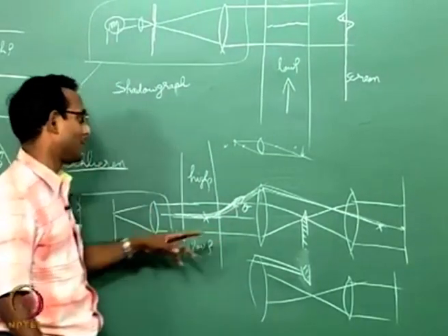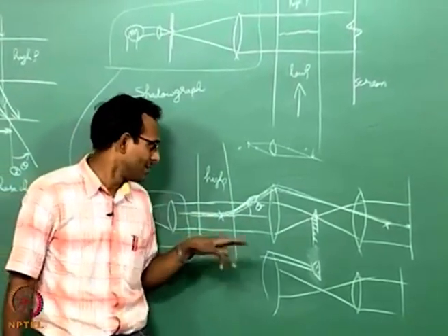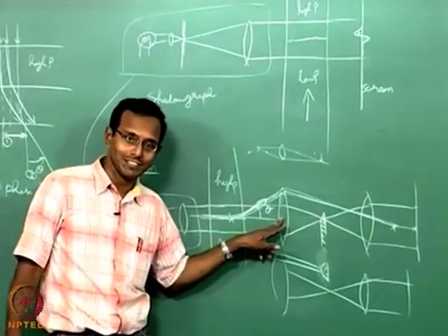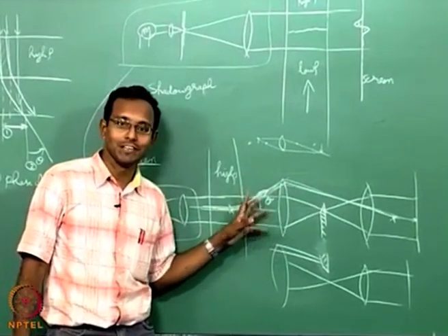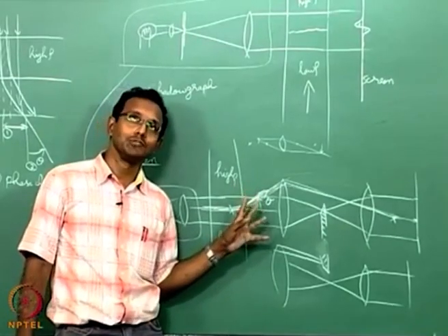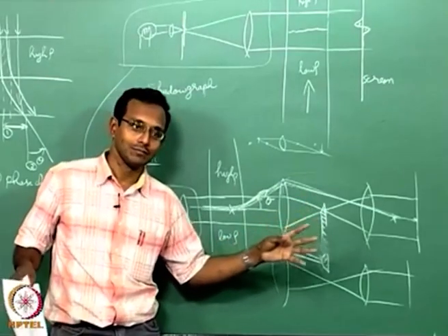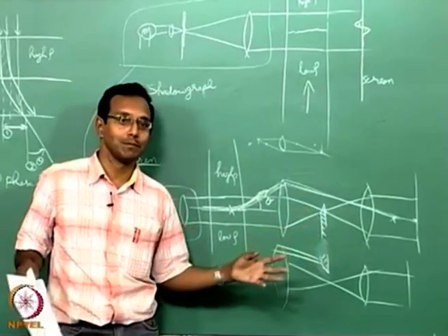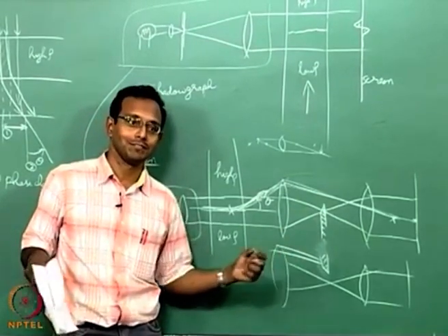In Schlieren setups, typically people use a long focal length. We have Schlieren setups which use mirrors instead of lenses. We have not drawn that picture yet. This particular lens, if we think about focal lengths, I have used one which was 6.5 feet long. That is the kind of lengths people will think about. At least we should think about more than 1.5 meters typically.